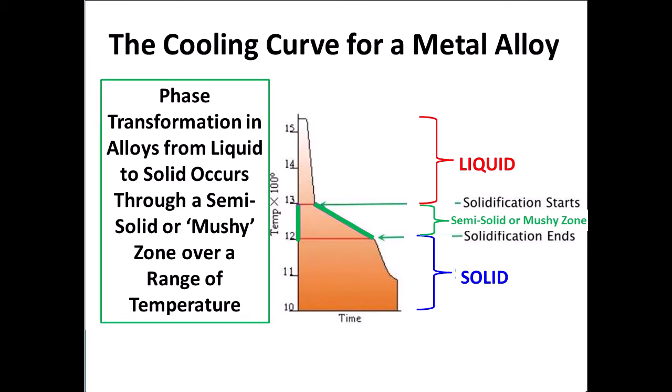The binary liquid exists above the liquidus curve, the upper red curve. Since there's a single-phase liquid present there, the composition of the liquid is 35% nickel, 65% copper. Upon cooling, when we hit the liquidus curve, the liquid will begin to convert some liquid to solid.